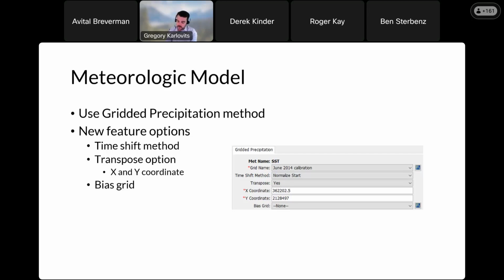The other part of what it does is it lets you control those values externally. And when I say externally, I'm talking about the uncertainty analysis and the optimization trial. So anybody who's played with those features in HMS probably just got a little devilish grin and realized where we're going with this. Those coordinates now being able to be shifted in a structured way is how we achieve SST or storm maximization, because we now have a handle that we can grab and move these storms around.